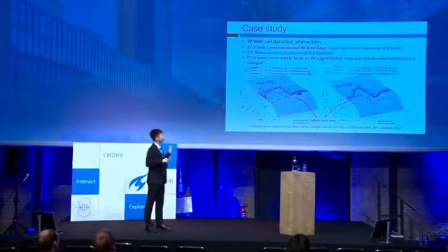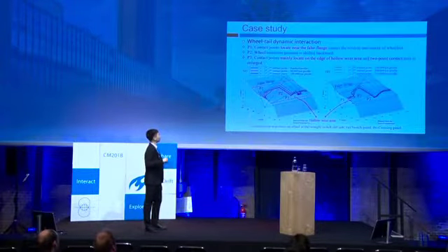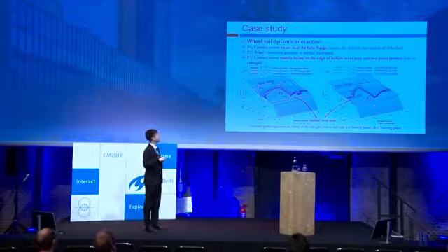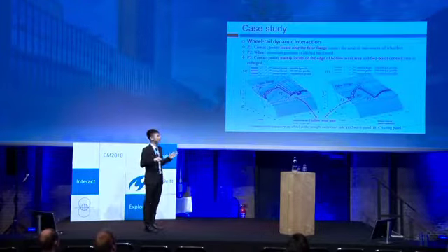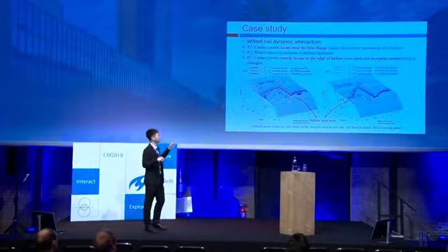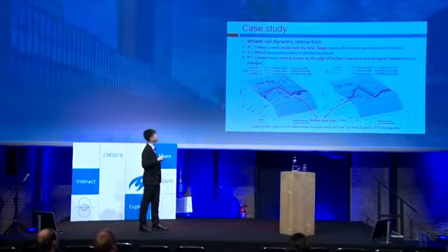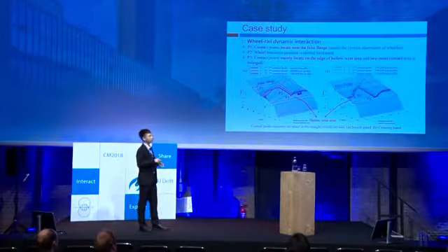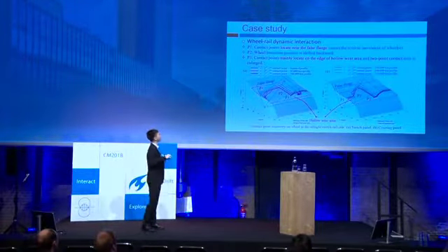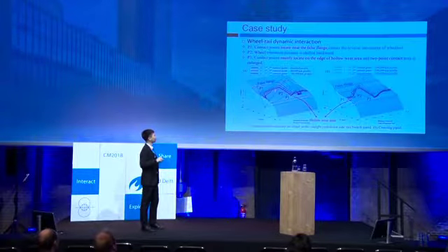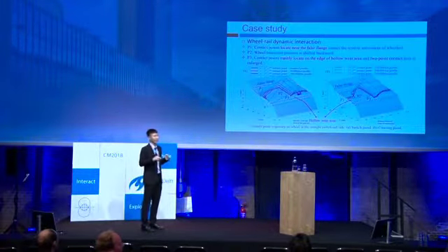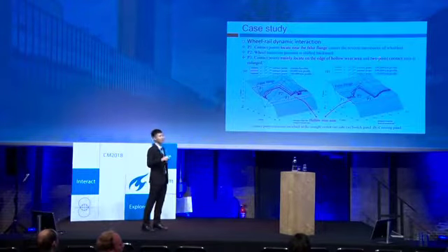I divided these figures into 3 parts. Part 1, Part 2, and Part 3 mean the contact point position before the wheel transition, during the wheel transition, and after the wheel transition from the stock rail to the switch rail. The rectangle means the hollow wheel area, and the outside edge of this area means the flange. So we can find from these figures that for part 1, the contact points are located near the flange when the operation mileage is large. It causes the reverse movement of the wheel set.